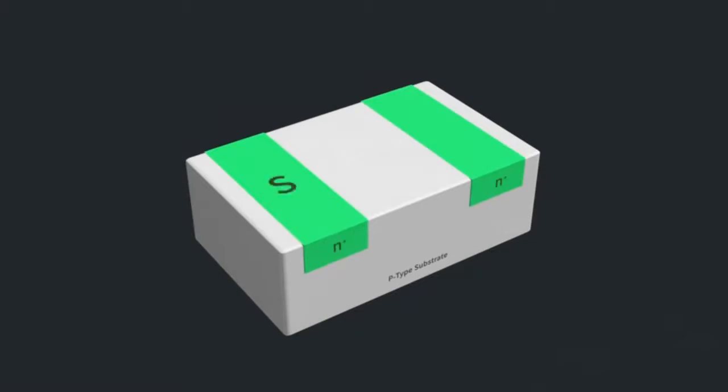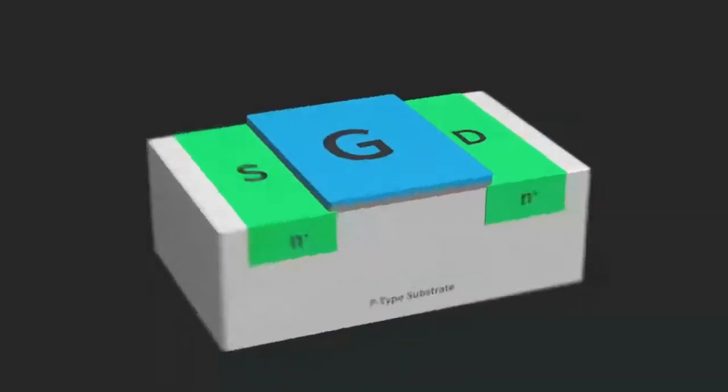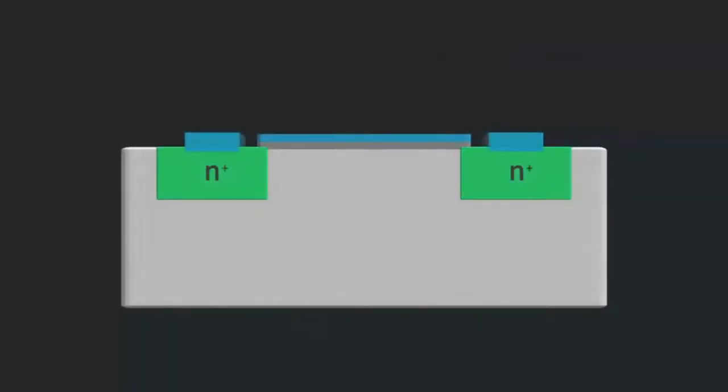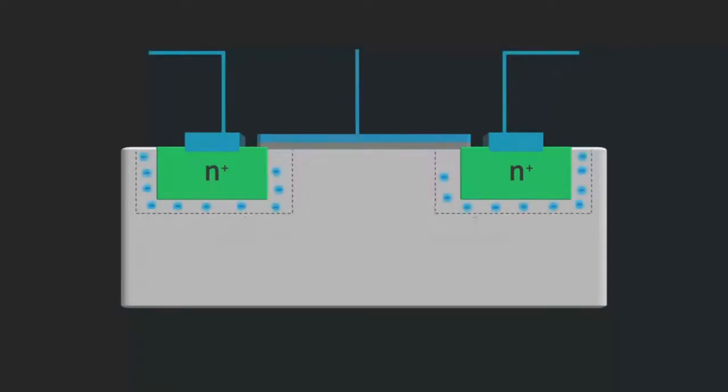So the MOS works simply by using these two regions, the source and the drain, and between these two regions we create a capacitor, okay, which is the gate and the substrate. And this works just by accumulating charge below the gate. Okay, so this is the channel, and in this channel we accumulate the charge. So by definition, our transistor is using a capacitor. So in fact, we have capacitors between gate and source, gate and drain, gate and bulk, drain and source and bulk, and so on.